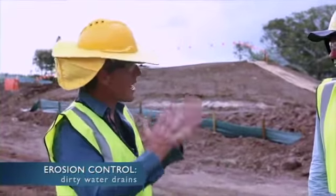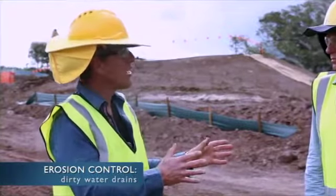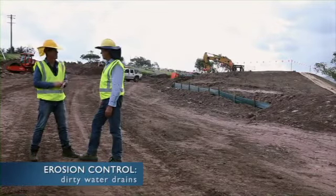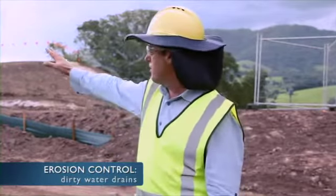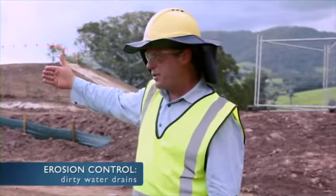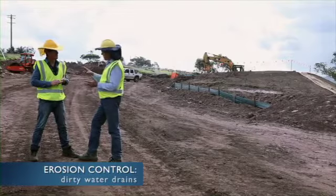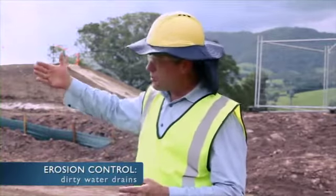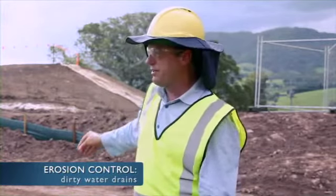So we're talking about cut-off drains which carry concentrated or dirty water across the site. But in a downpour, won't they cause erosion in themselves across the site? No, they're actually essentially erosion control, Pete. So what we'll do on a major slope like this is we'll set them in at a regular interval, maybe about a 20-metre interval. And what that's going to do, it's actually going to reduce the slope length the water can act on that exposed soil, so we're going to get less total erosion. The cut-off drains will take that dirty water and transfer it to our major controls downstream.